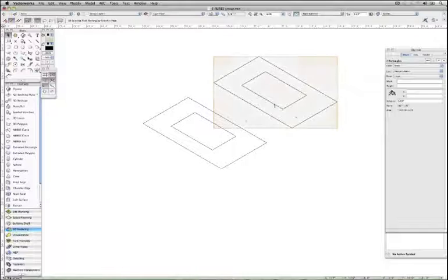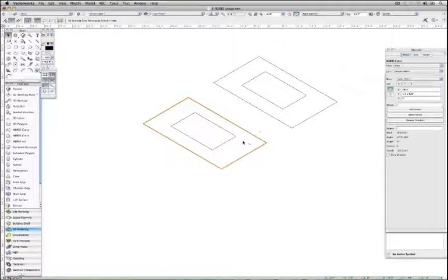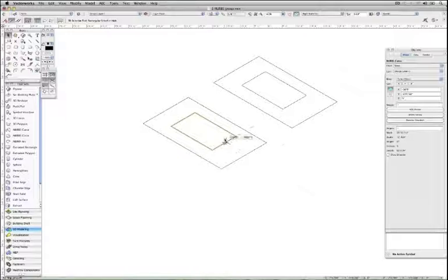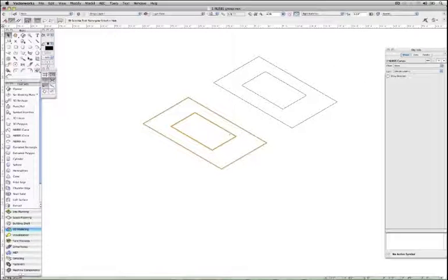But now, moving down to these other 2 rectangles, I'm going to convert them to NURBS, once again using a keyboard command. But you can see it there in the Object Info palette. And once I do that, I'll simply group them just like I did for the other 2. Okay, so now I'll go and select the Push-Pull tool, and we'll see what happens.